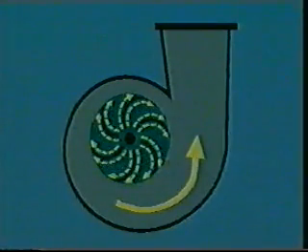However, as the flow rate becomes too small, the gas will separate from the vane tip. As a result, that vane passage loses the ability to increase the gas pressure. When that happens, there will be a slight amount of backflow from the diffuser until lift is regained.